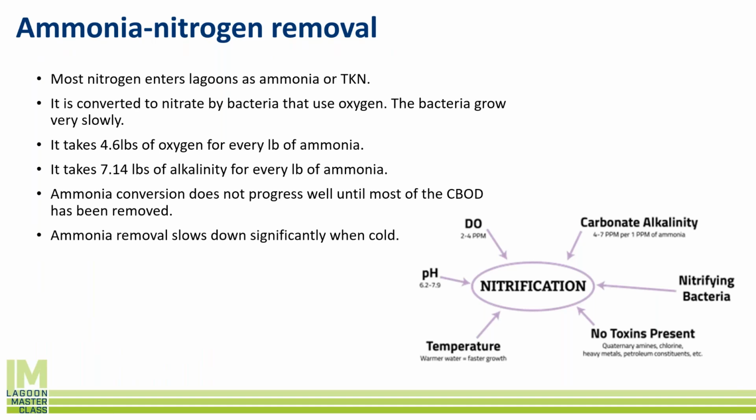These bacteria grow very, very slowly. They are a real hassle. They're finicky little bacteria. They're kind of wimps. So there's a lot of factors that contribute to their growth. One of those factors is alkalinity. A lot of us don't measure alkalinity in our lagoon systems, but alkalinity is a way to measure the amount of inorganic carbon that's in the water. And the measurement's actually calcium carbonate when you look at your testing equipment.